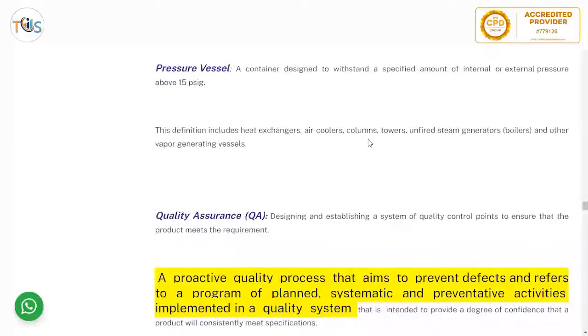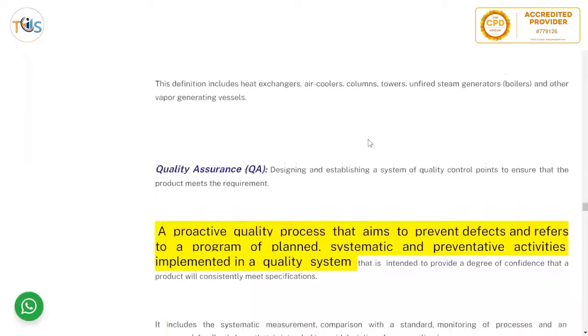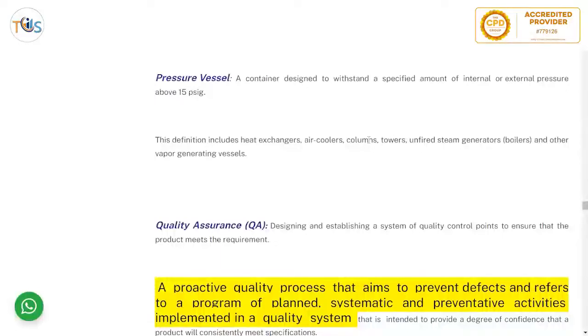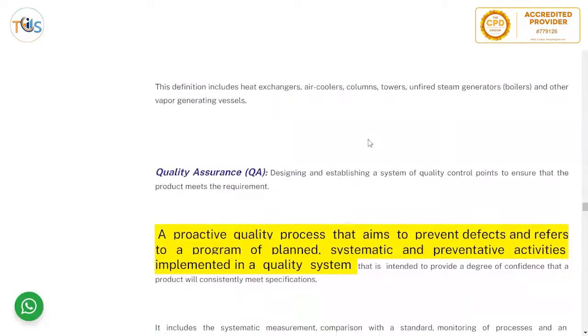You cannot revise a PQR, but you can revise a WPS on non-essential parameters without changing the PQR. But if you want to change an essential parameter of a WPS, then a brand new PQR is needed because the essential parameter changed.